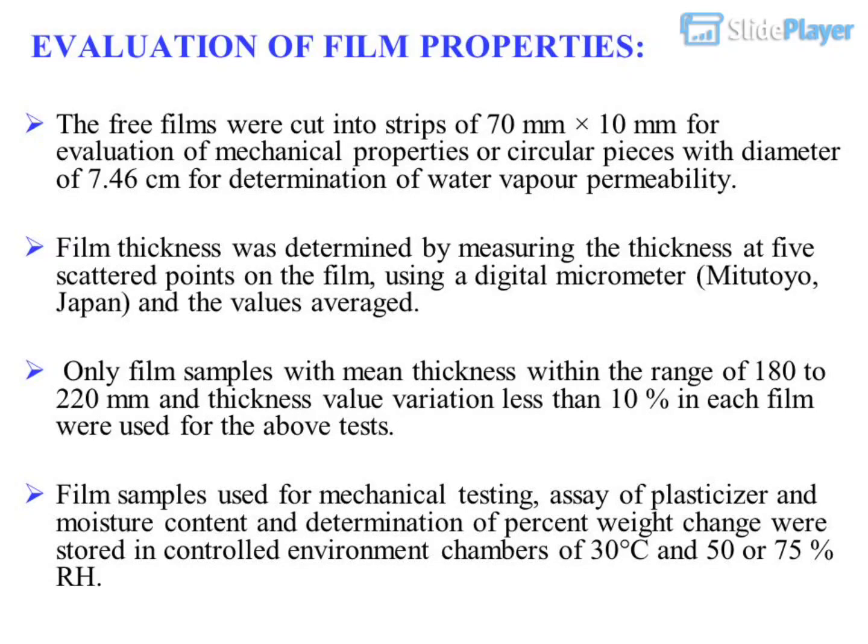Film samples used for mechanical testing, assay of plasticizer and moisture content, and determination of percent weight change were stored in controlled environment chambers of 30 degrees Celsius and 50 or 75% RH.